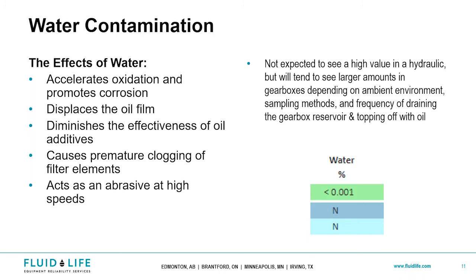And of course, this is going to cause some clogging. It's going to get your filter elements out of balance, and you might have to replace those more frequently. And the crazy part about water as well is when you start getting it really amped up in speed, it can be an abrasive element as well.